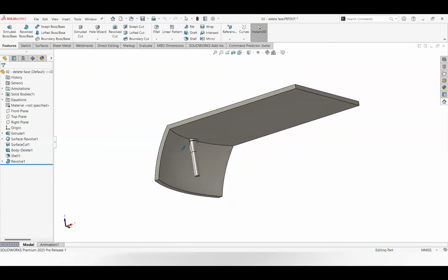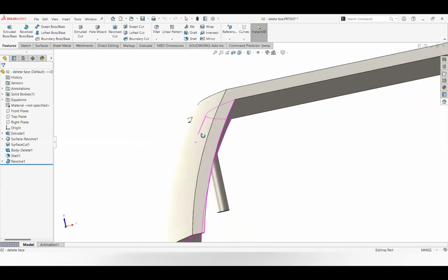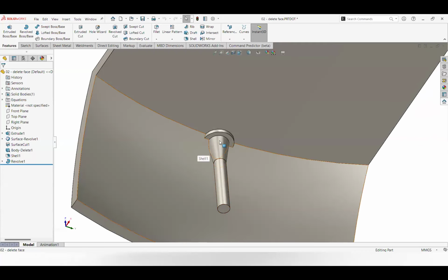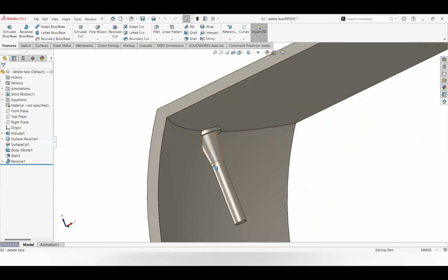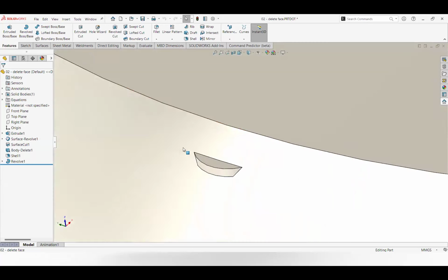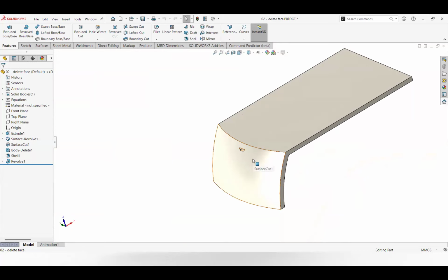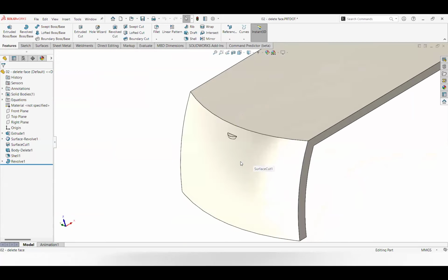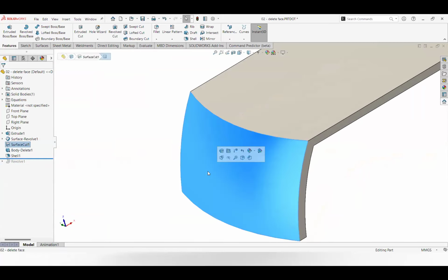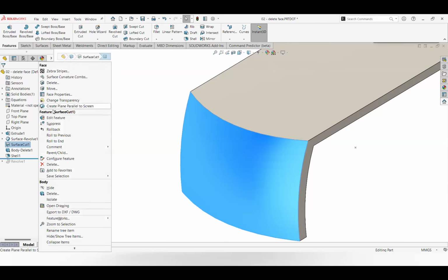Like this is a classic. Got a plastic boss, and I had to add, obviously this is fake, but you have to revolve on some standoff or something inside, and well, okay, the revolve happens to stick out the back. You can't really do a partial revolve here because you need it on the inside. So yeah, you could just do another revolved cut out here. I've seen people roll back before the revolve and copy the surface, revolve it, and then use the surface to cut. Yep, that works too. But it's much easier if,